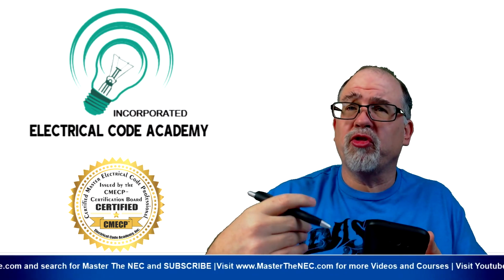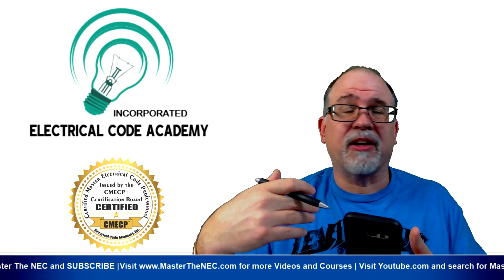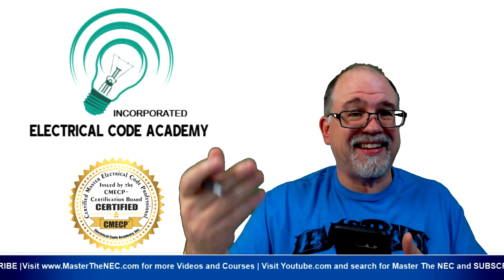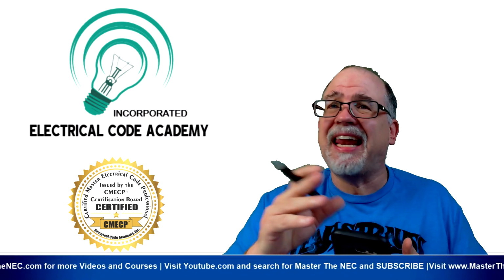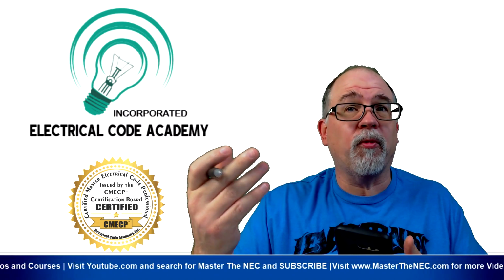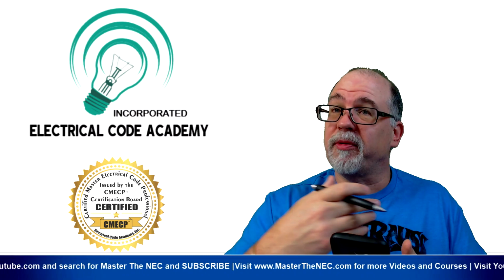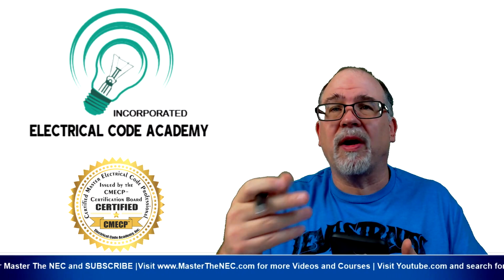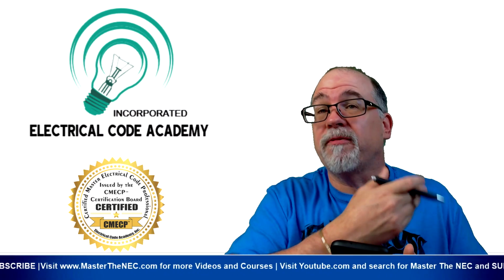We typically are going to use 125%, because depending on what we've got for conductor protection and whether or not they're continuous loads, we also want to utilize this primary protection to protect the conductors. And of course, in 240.4, we need to protect conductors at their ampacity. We have no allowance in 240.4 to do things like we do in motors or HVAC systems in Article 440, or motors in 430, where we have a short circuit ground fault protection that can be rather large, but the motor's branch conductors feeding it can actually be much smaller, so they don't have the same ampacity as the breaker or fuse they're terminating into.